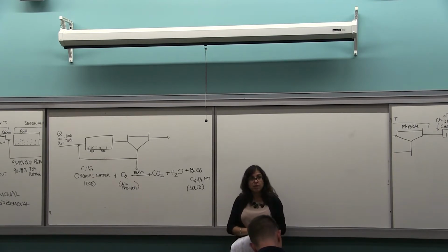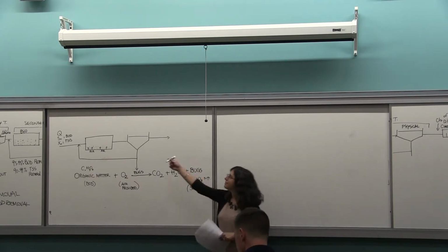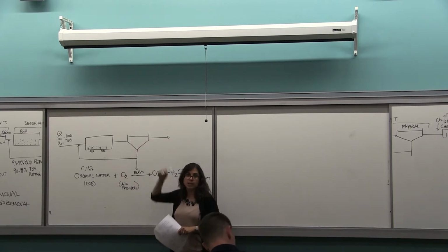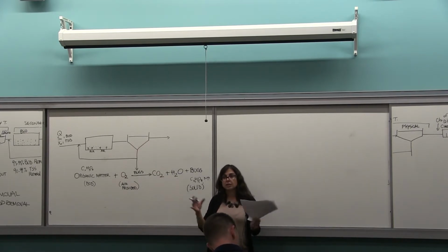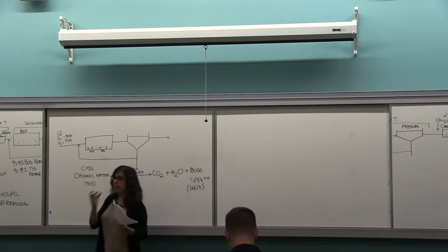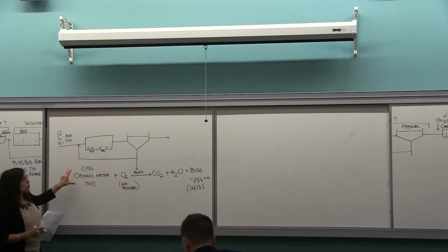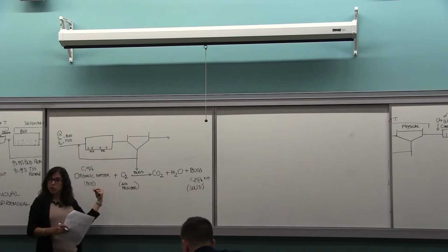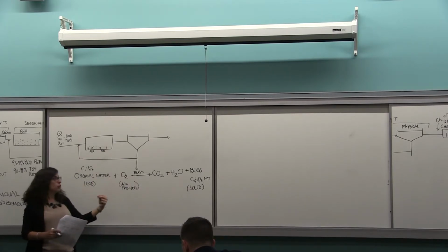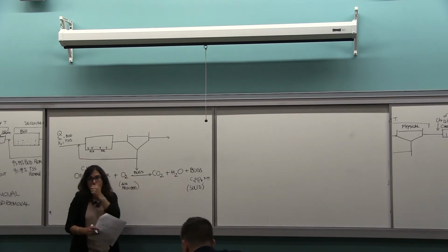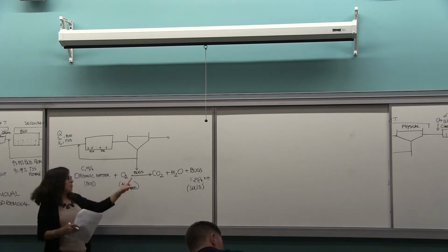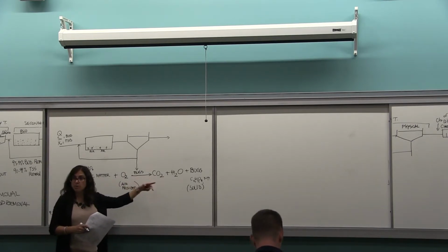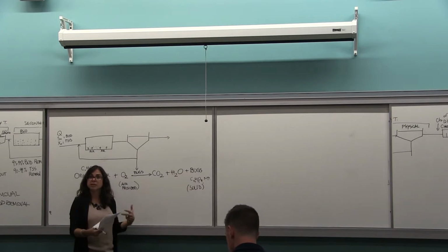How do we remove solids? Physically remove it in a clarifier. So the secondary treatment allowed essentially to transform organic matter from soluble organic matter to CO2 and water. Some of the carbon goes here, some of the carbon goes to build new bacteria.